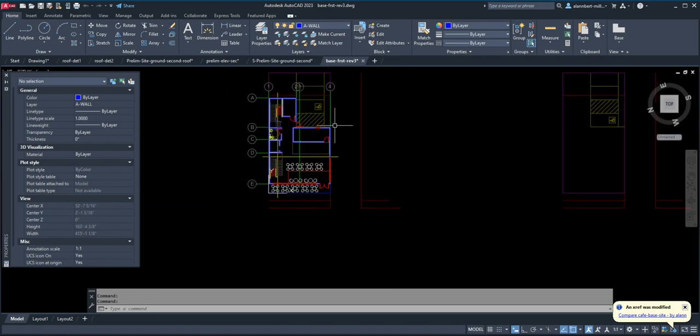If you're still changing the floor plans, then you might need to adjust your drawing system, because once you change your floor plan, you have to redo the ceiling plan based on it. That's why most reflected ceiling plans are done when the floor plan is in the final stage, or has been signed off to be final.